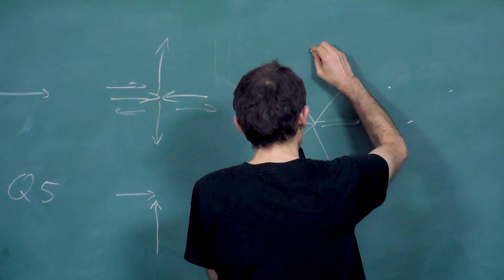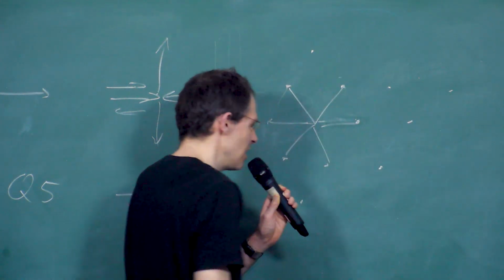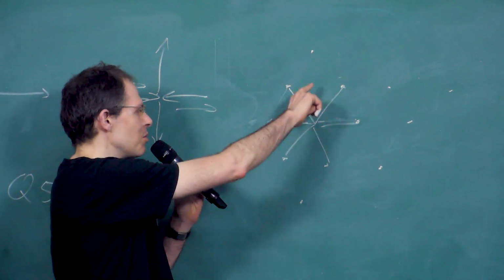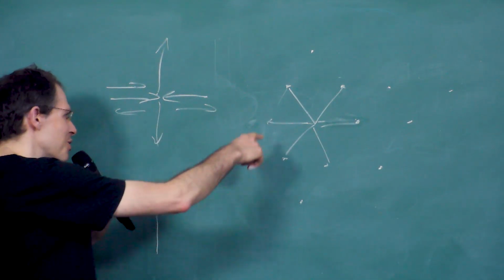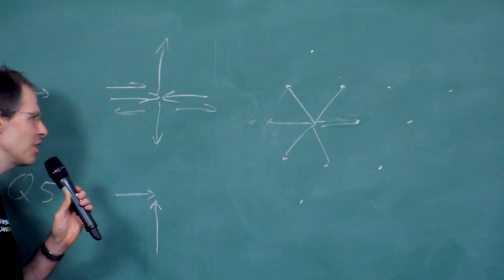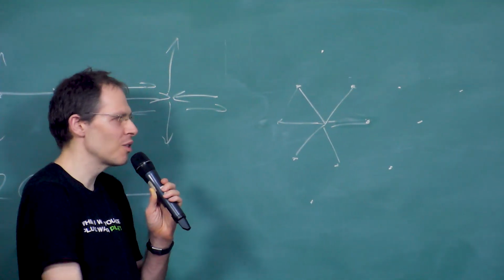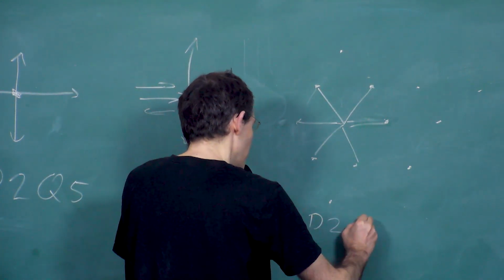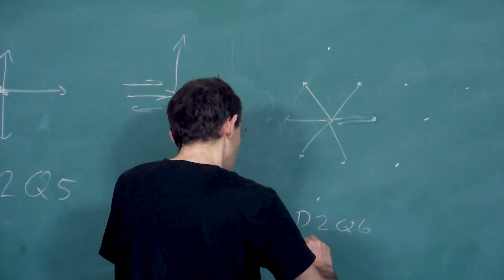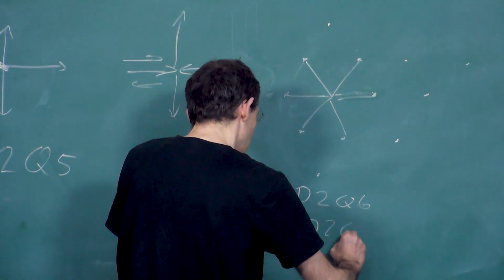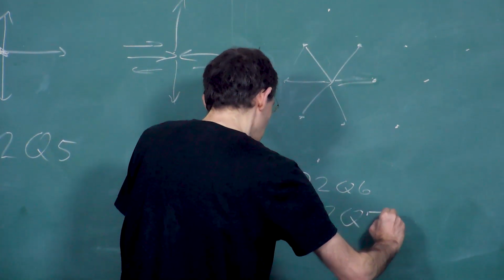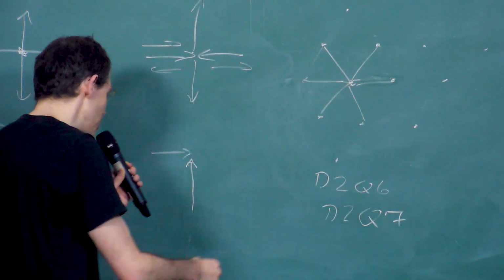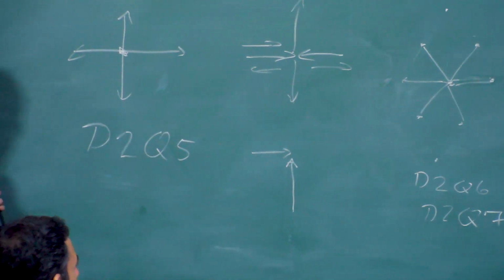They would continue on like this, and in this it is actually possible to carry momentum laterally. So if you use this configuration, even if you have no resting particle, so only 6, the D2Q6, or the D2Q7 if you have a resting particle here, then you can do lattice Boltzmann with this. It's actually possible.